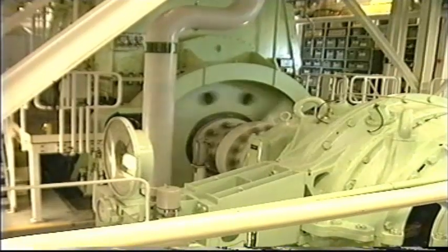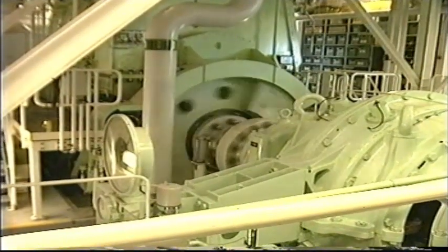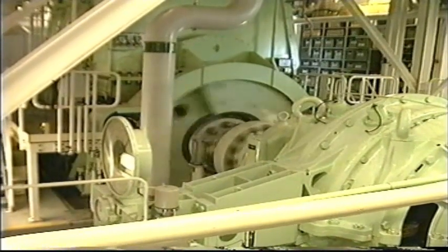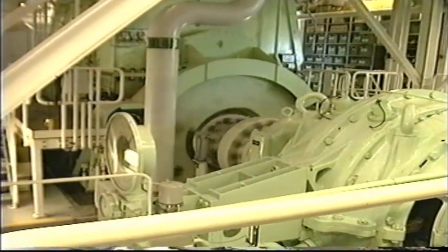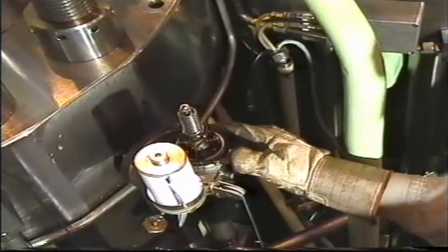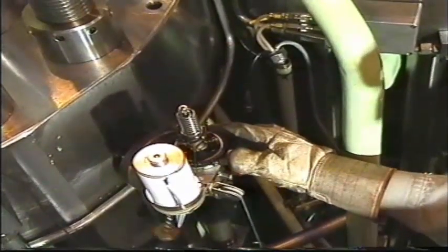Start the engine and run it up to a load corresponding to the break point load, and thereafter to 100% MCR load. Use the indicator drive or PMI system to adjust the load so that it corresponds to the breakpoint load and 100% MCR load. Note down the fuel pump indexes.